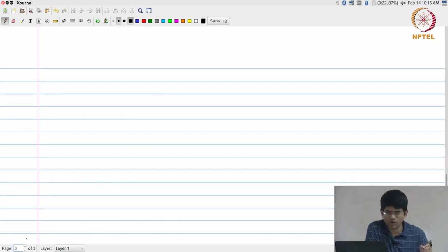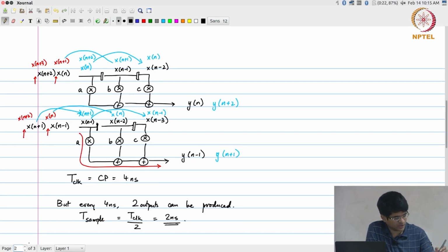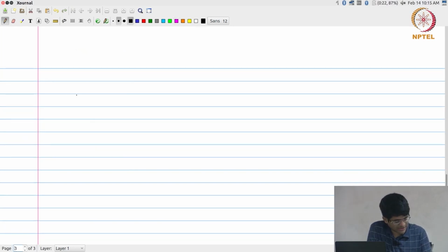The twist that we can observe as far as parallelism is concerned is, if you go back and look at this diagram over here, you will notice that, for example, this x of n minus 1 is occurring in two places. Similarly, x of n minus 2 is occurring in two places, right, and I am effectively having to put two registers over there and generate those data separately. What if I try and sort of combine that? What it would look like is something like this.